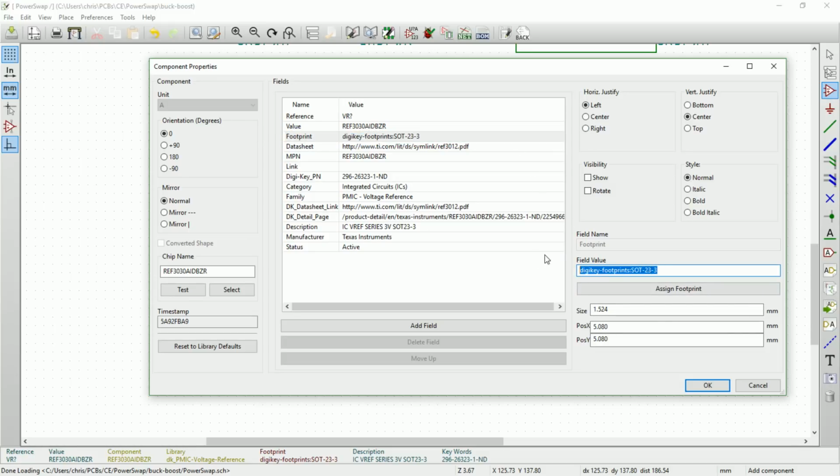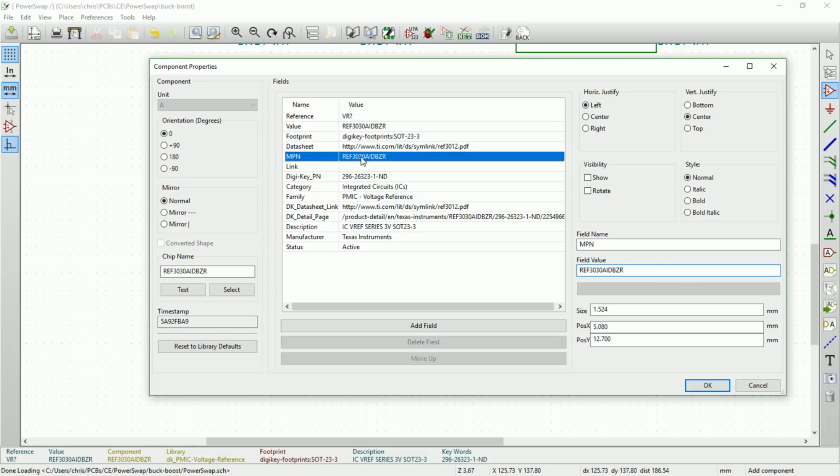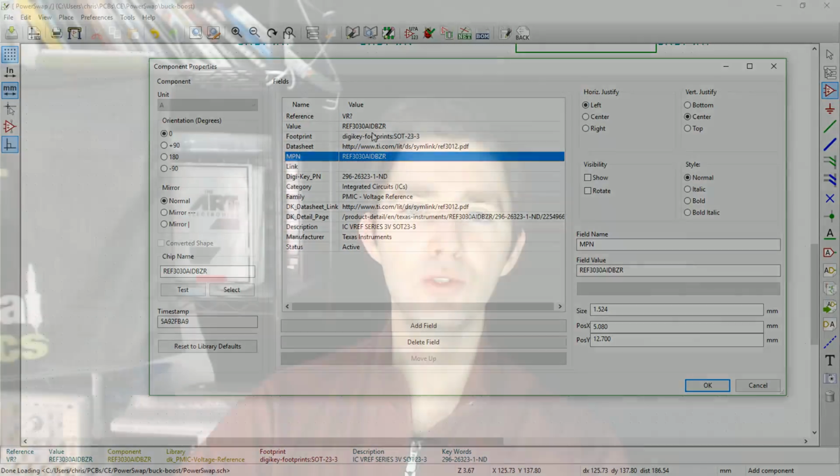Now this is actually very different than most KiCad parts you'll ever deal with, because this is what it refers to as the atomic library. This singular part number, right? So this Digikey part number, or really the manufacturer part number, is now tied. So this symbol that we're looking at right now is tied to the footprint. Now that's not actually a normal thing within KiCad.